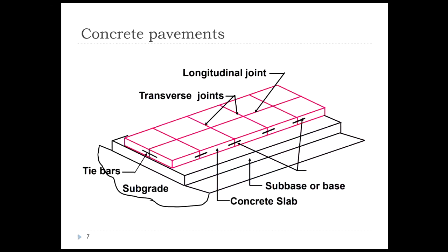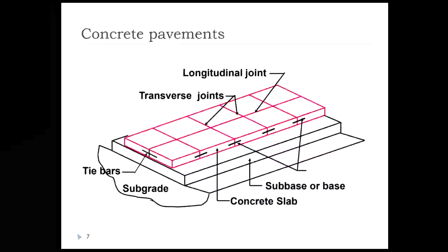Let us brush up our idea about concrete pavements. In the case of concrete pavements, you typically see panel concrete pavements. Okay, you find panels of dimension 3.5 by 4.5 meters. It can vary in the case of low volume roads. Now, you find transverse joints.